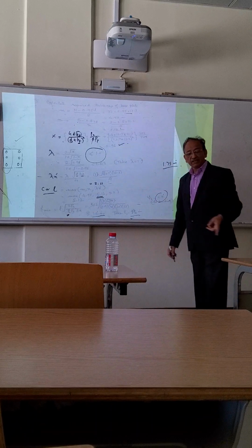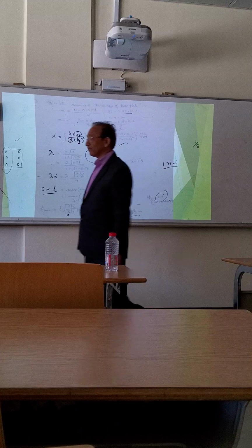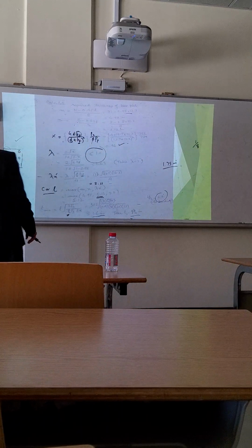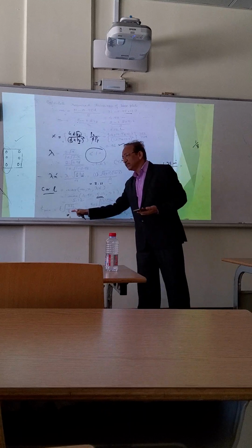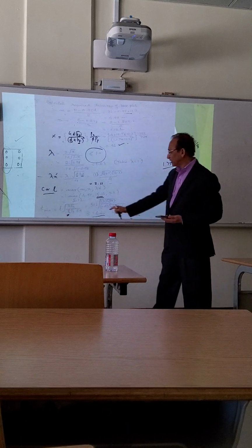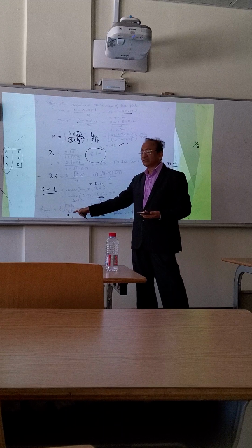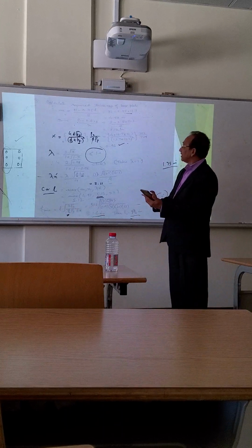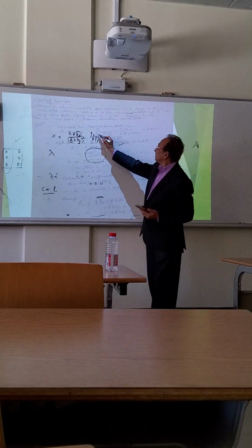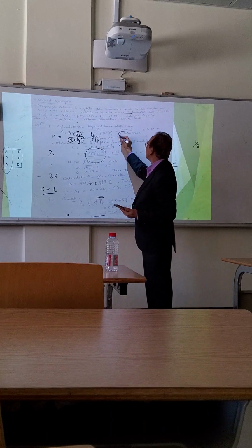Initially that value 0.65 was taken for the compression case, in the case of concrete, whereas this phi is for your steel plate. That's why we are using Fy here. And when we are talking about concrete, we take F'c, which was here, this one. So this phi was 0.65.